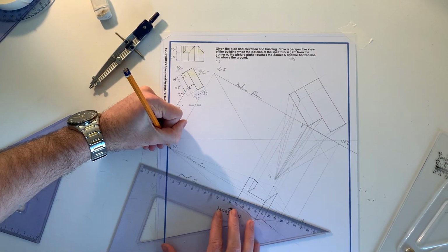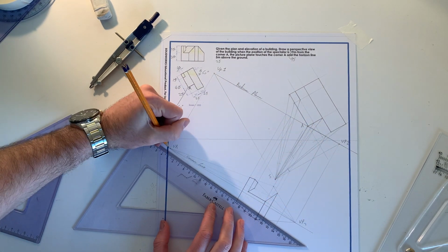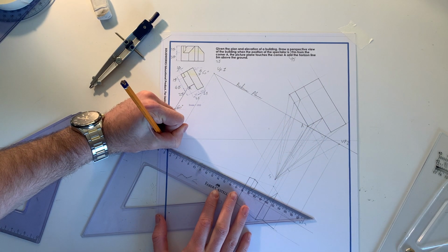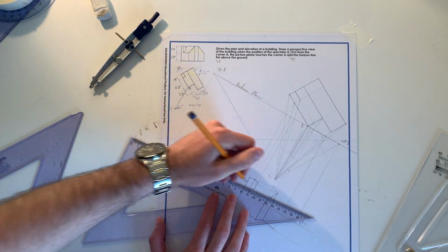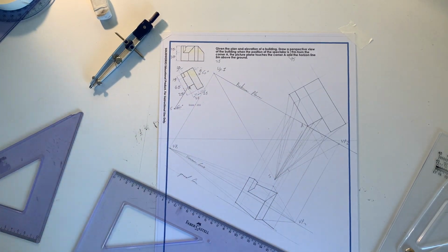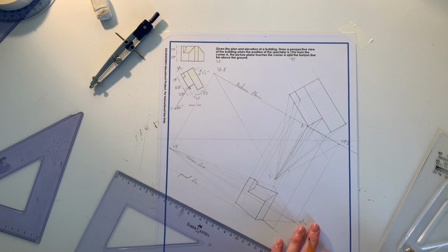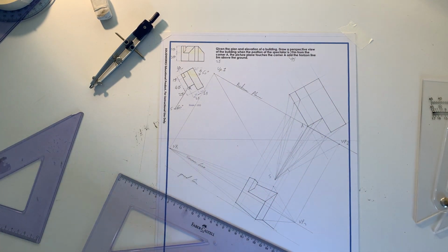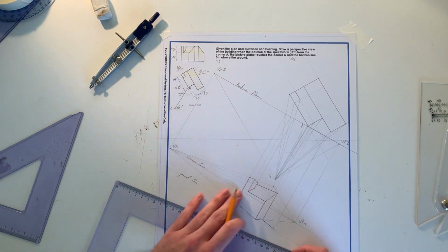So again, I'm just following the same procedure as always, locating points above here, dropping down and also joining back to the VP and slowly building up results. Sometimes it takes a while just to think about it and look at what you're seeing. A lot of visualization is required to help you construct this. If you get caught at any point, just try to work back along the points you're looking for and see what the next point can bring you, finding the next corner so you can make the next surface. For example, here now I have this much completed.